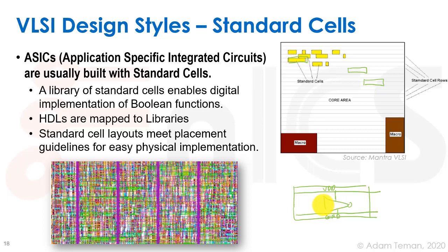We can't get as high an optimization as in full custom design, but this still gives us the freedom of putting each gate almost wherever we want to put it, and being able to use whichever gates we want, which is really good. But it also is very expensive, and once we design this thing and fabricate it, if we put an inverter here, that inverter is going to be there, and if it's connected to this inverter, it's going to be connected, and we can't change it after fabrication.